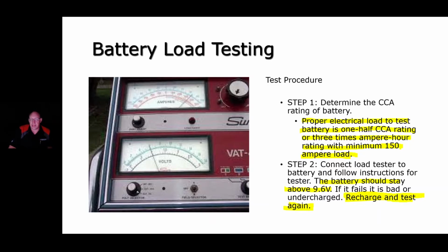So think about that. But here, you connect the load tester to the battery and follow the instructions of the tester. Over here on the tester, you will see that there are a few things that need to be switched. Are you testing the charging system, or are you testing the battery by itself? You need to know what you're testing, and you need to flip that switch right there.